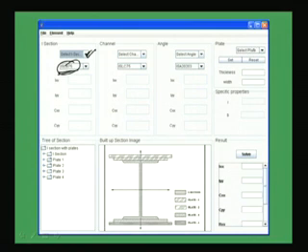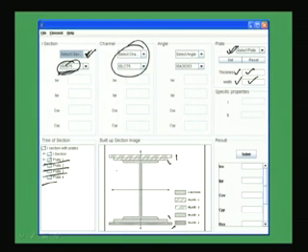Then you can choose the plate. You see, plate 1, plate 2, plate 3, plate 4, because in our software we have kept the option of one plate here, one plate here, one plate here, and one plate another. So 4 plates are there. The 4 plates may be of equal width and equal thickness, or may be different. So the plate properties have to be given here, thickness and width. So you have to select one plate, then give the thickness and width of that plate, right? Here also the option is there, you can provide some channel also. If you want to provide some channel, you can have that option also by clicking here, say ISLC 75.